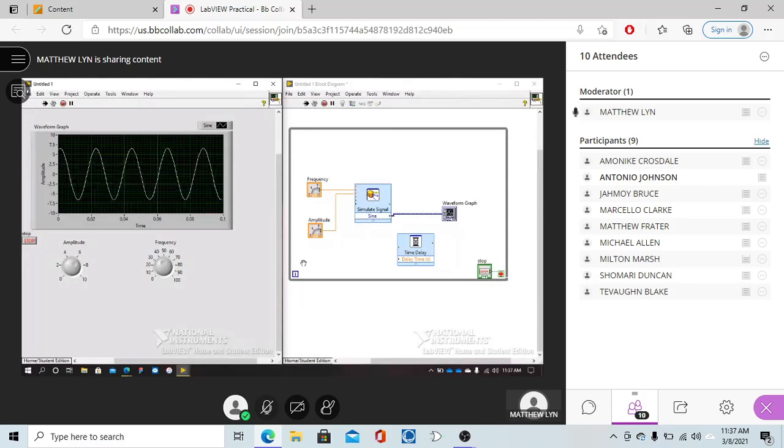So you need to add a control to the stop button. I right click it and press create control. Go again. The stop wasn't there, and there was a broken arrow for the run button. You see it? So the loop condition terminal is not wired.